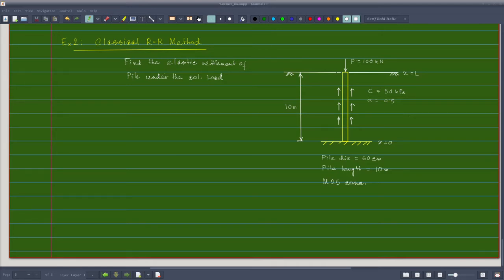We are assuming constant cohesion. That takes place in case of over-consolidated clay. In normally consolidated clay, usually cohesion increases with depth linearly. And then we take an adhesion factor of 0.5 for clays usually, so that the frictional resistance around the pile will be given by alpha into C. Okay, that is what is adhesion.